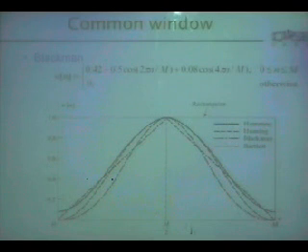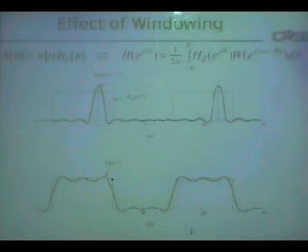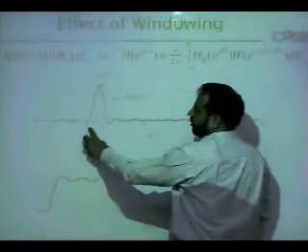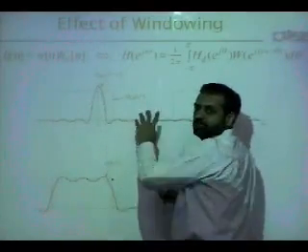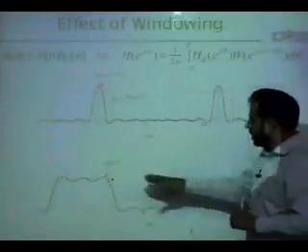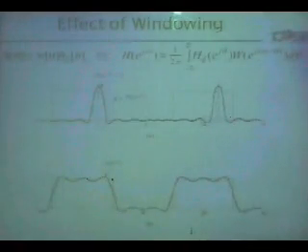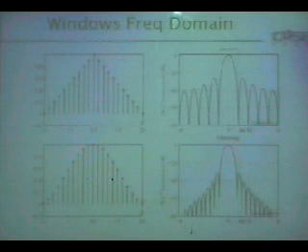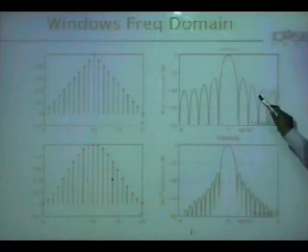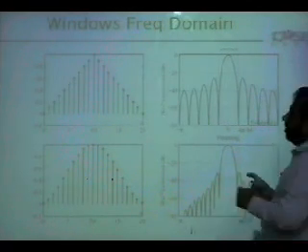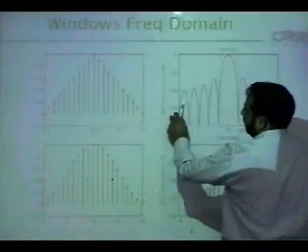So what is the trade-off? They are just playing with the Fourier transform of the window, because we know this Fourier transform is causing these ripples, the transition and the other ripples. This is the Fourier transform of a triangular window, at minus 40 dB.